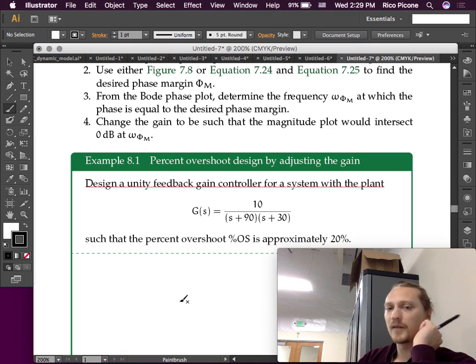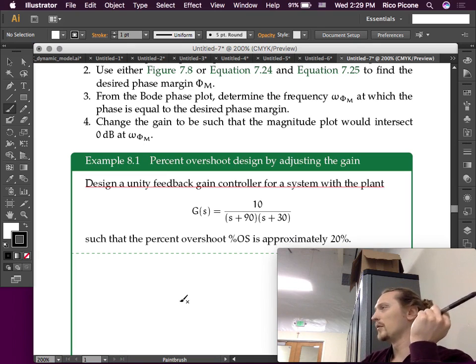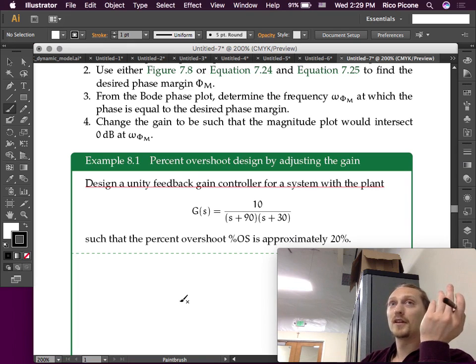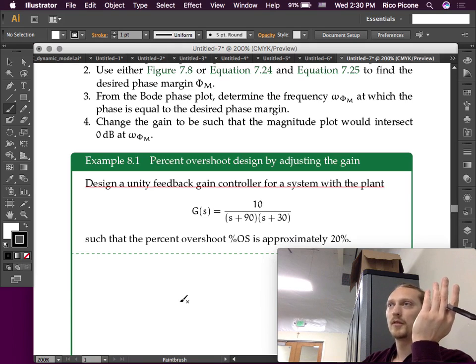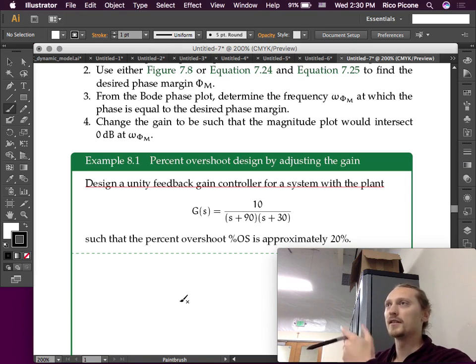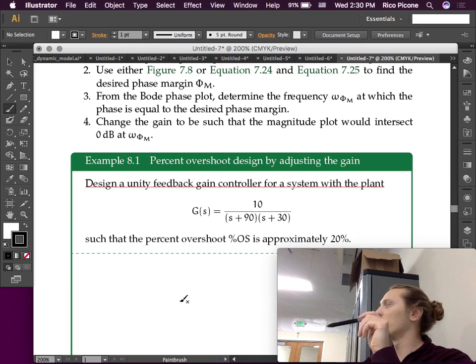And then also it's stable, right? The open loop transfer function is stable, which is good news. If we're thinking in terms of Nyquist here, our number of open loop poles in the right half plane is 0. That means that we need 0 encirclements of -1 for stability.